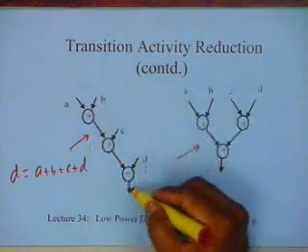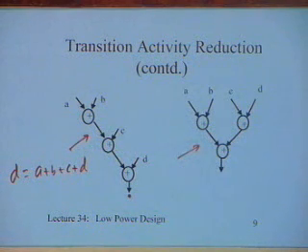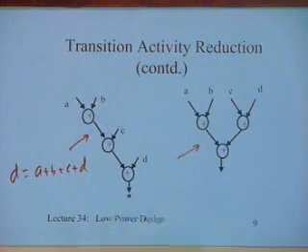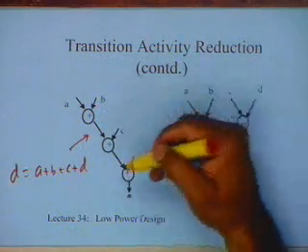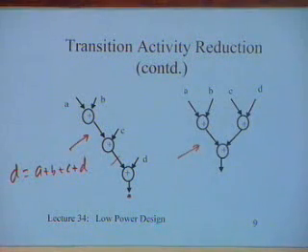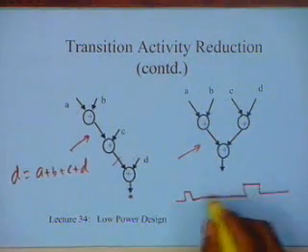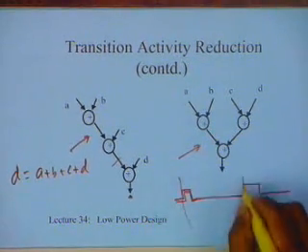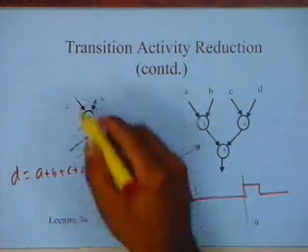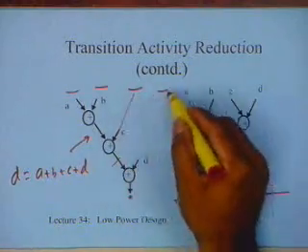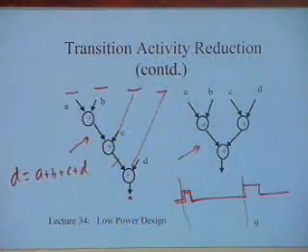If I implement it in this manner and monitor the activity over here, it is all within the clock cycle. I am talking of a combinational circuit, so even within the clock cycle you can see what activity happens over here. Now there will be some value present here at the beginning of the cycle. Let us say everything is happening within 2 clock cycles, and the output is registered. So if we start from the beginning of the clock cycle, when data gets registered, data also gets registered in all these registers which store A, B, C and D.